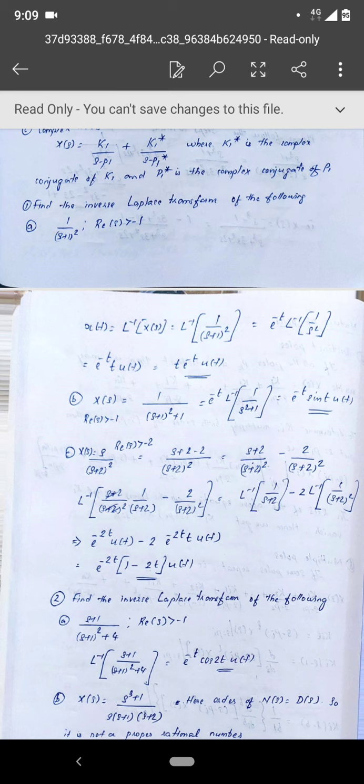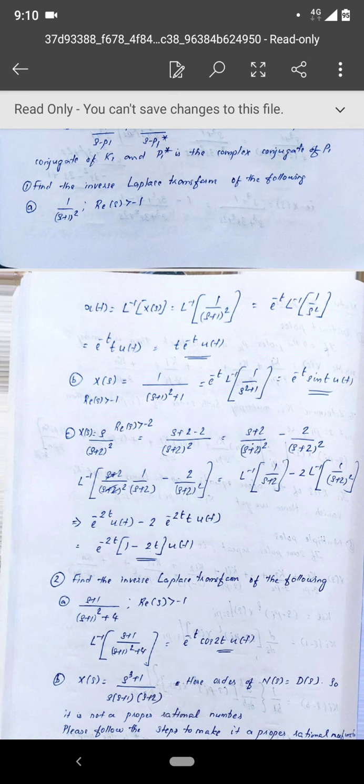You have to keep that in mind, because even if we have learned the partial fraction method, when you see a question, first you have to check whether that Laplace transform is in any form of those standard signals. You know the Laplace transform of u of t. What is the Laplace transform of u of t? It is 1 by s. So if you see a term in terms of 1 by s, you can straight away write the inverse Laplace transform. No need to find the residues and do the partial fraction expansion.